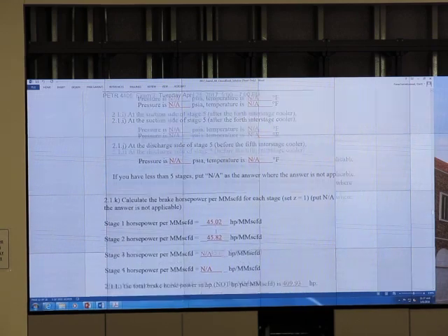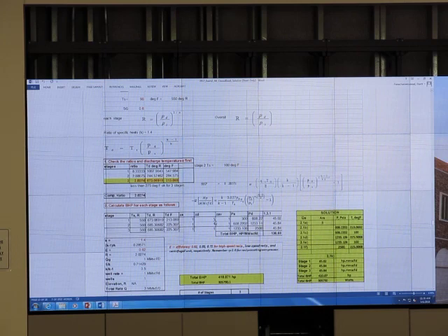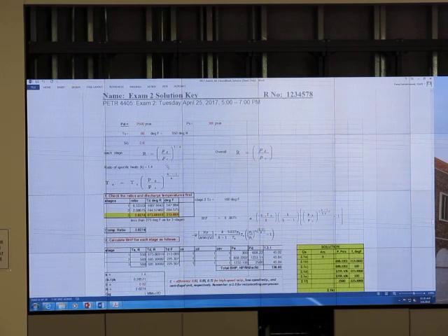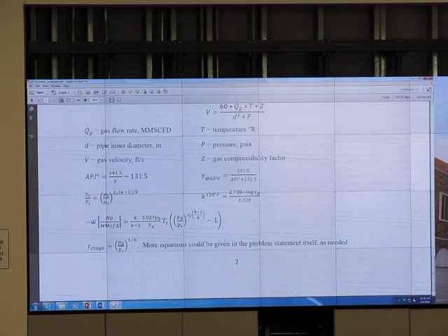To do all this, the grader uses Excel, but okay, you just put the value into that equation and you specify the 3 stages. And oh, look at that equation. It was given, right? I gave that equation too. Oh, did I have that equation? Yes, it is there. Compression ratio per stage equals that: PD over PS, to the power of 1 over N. So R of each stage, and PD and PS are what? Initial suction and final discharge, right?